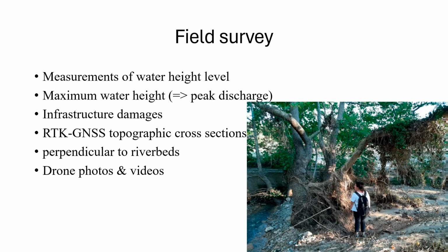A field survey took place following the flash flood of 9 August, focusing on the areas mostly affected, namely the alluvial fans of Psahna and Politika. The field survey included the following. A. In situ measurements and observations regarding the water high level and extent of the most characteristic sites in the upper part, the urbanized part, and the lower part of the drainage network, approximately 1.6 square kilometers at Psahna and 1.7 square kilometers at Politika.